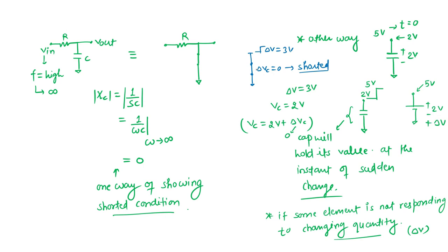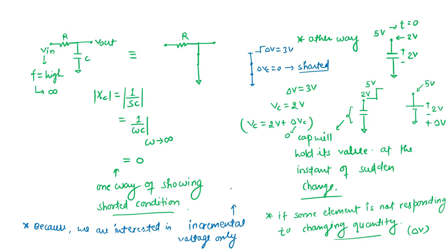But in our analysis, this thing I should make clear here, because we are interested in the incremental voltage only, our cap has an incremental value of 0. It simply means my cap is shorted.